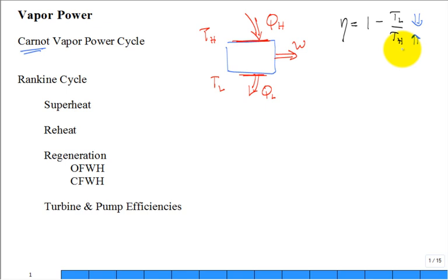That applies into the Rankine power cycle. That same logic. We want to bring in all of our heat at high temperature into the working fluid, into the steam generator, boiler, etc. We want to reject in the condenser, wherever we're rejecting it, at as low a temperature as possible. In the Carnot, it's all brought in at TH and all rejected at TL, but when we get to real operating power cycles, it's not all brought in at TH. Some is brought in at lower temperatures, some at higher temperatures. But the goal would be shifting it and getting as much brought in at high temperature.